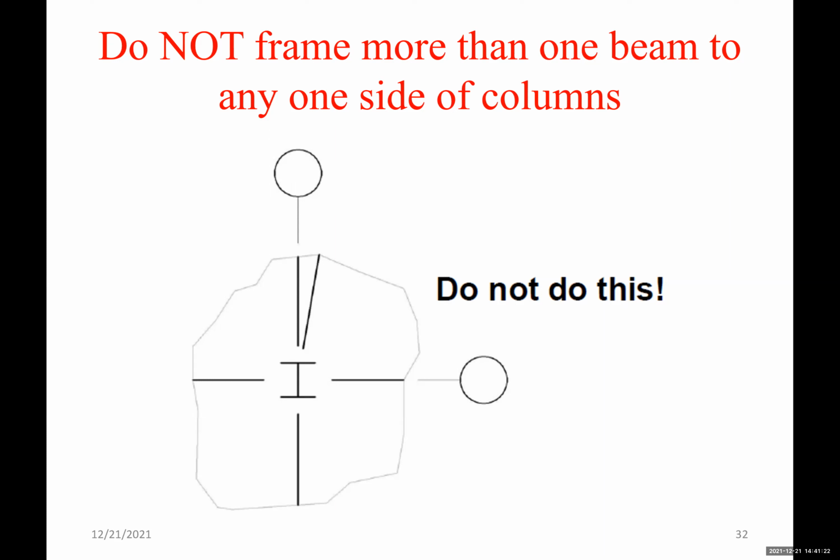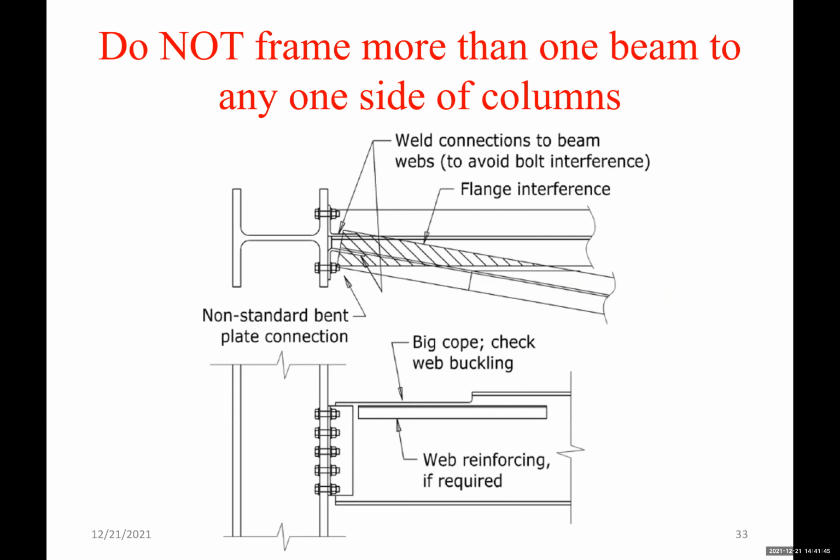column flange. Now, of course, on the drawings, this may be shown as a line, as we can see. It's just a line. But that line has actually geometric properties. Today, with the use of Revit and 3D modeling, we could see that, if we pay attention to it. But in reality, it will be something like this. So 2 lines are coming to the flange of the column, so there will be a conflict between the flanges, and we have to cope the flange to allow framing it.